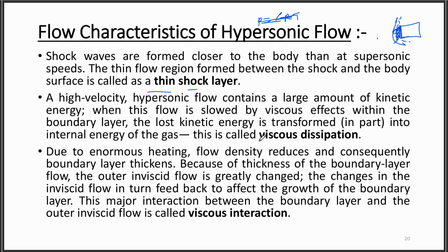The second characteristic is viscous dissipation. Inside the boundary layer, the velocity will suddenly become zero at the surface. So a large amount of kinetic energy is converted to thermal energy due to the viscous effect.